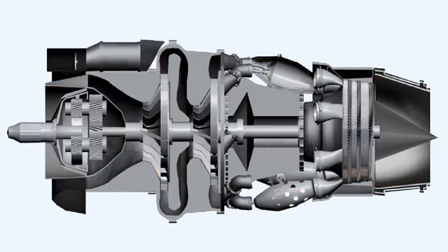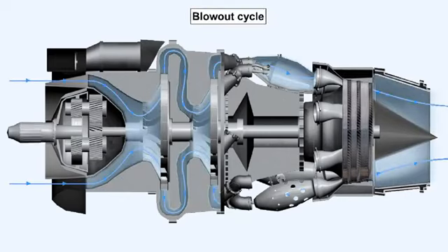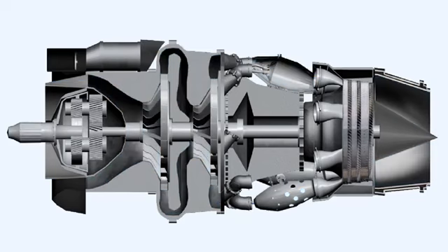Supplementary to these basic prerequisites for engine starting are two other requirements which satisfy servicing essentials. The necessity to motor over the engine with no igniters operating. This is sometimes called a blowout or motoring over cycle. The necessity to motor over the engine usually only occurs when there's been a failure to start. A failure to start is sometimes called a wet start. The need for the igniters to be operated independent of the start cycle.